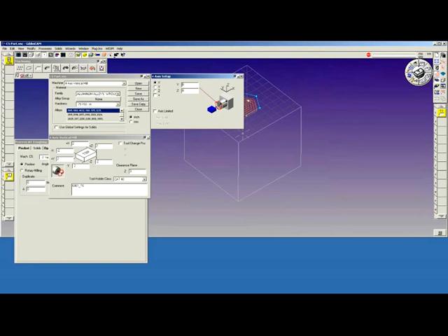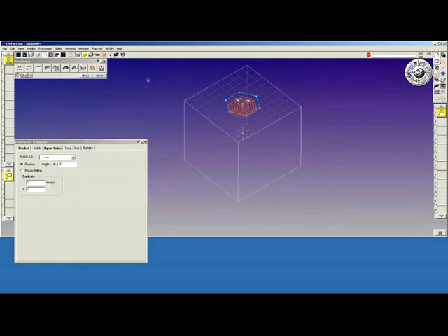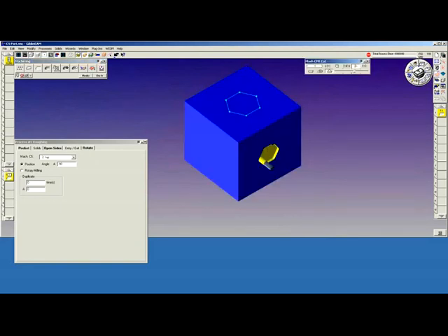So in order to bring that positive face up, if you remember the 4th axis setup, positive rotation was towards the operator. If I was to make that value a +90, I would do the machining on the back side because it would rotate forward. By typing in a -90, it'll rotate backwards. If I redo the operation, you see where the machining takes place. Turn rendering back on, and there's my machining. Even though the geometry is placed at the top, I can perform the machining on the front by changing the angle.